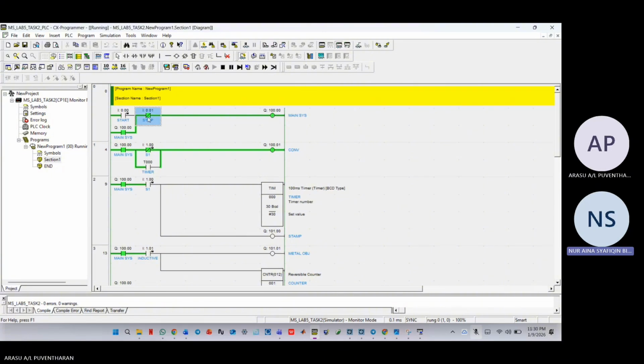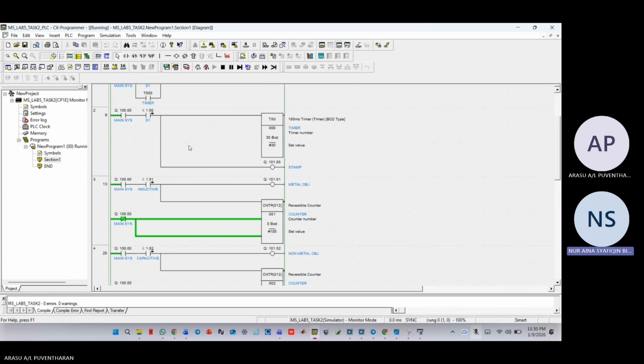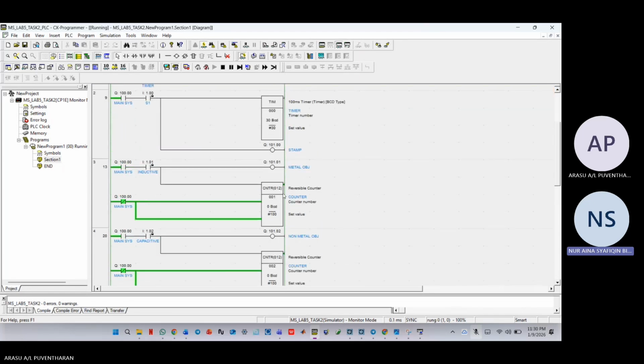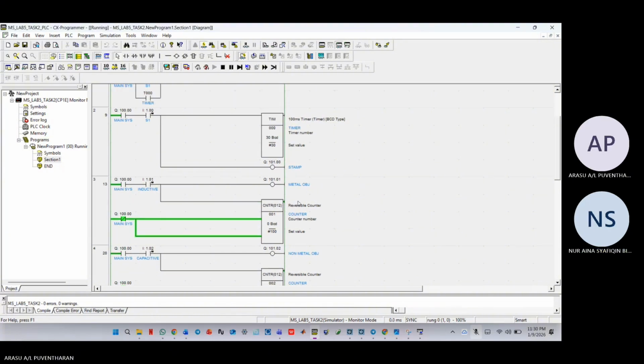Then, when the stop push button is pressed, the PLC unlatches the system, stops the conveyor, de-energizes all the cylinders, and resets the counter to 0, returning the system to its initial state.